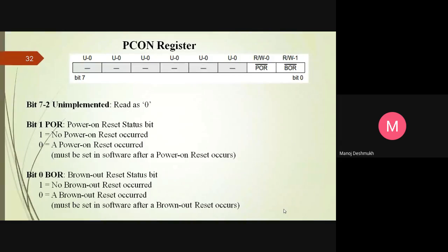See, this chapter is most important as architecture and most of the SFRs' working is included in this chapter. After that, the working of IO ports may be in the next chapter, I think. So various SFRs, how they are working, the bit size, initial status, readable, writable, and for which operation these SFRs are used, which is most important as far as we are concerned with the PIC 16F877 microcontroller. So study carefully the specific SFRs.